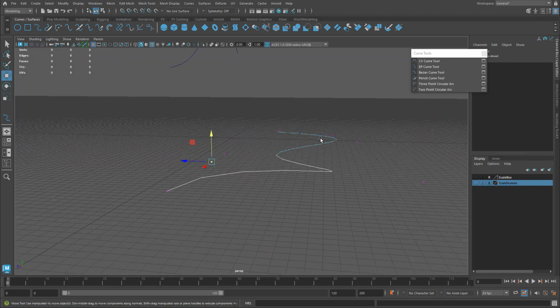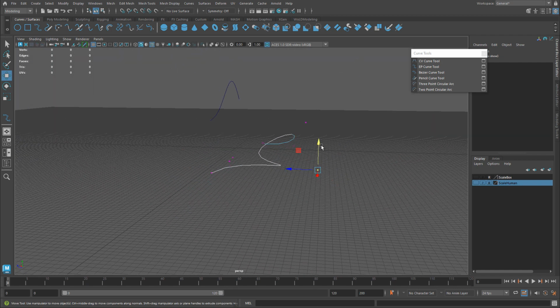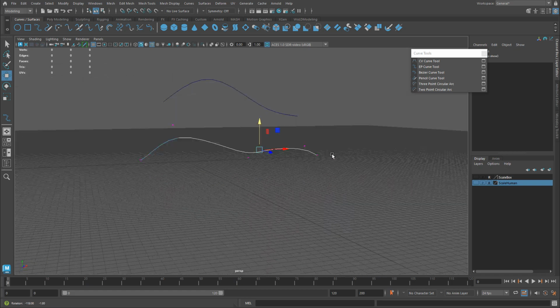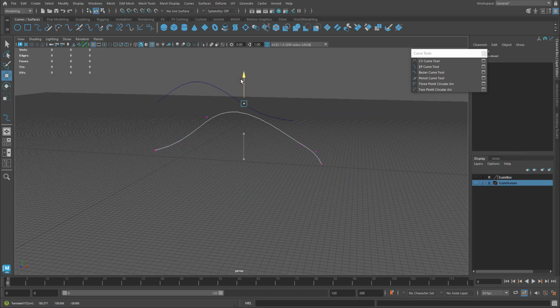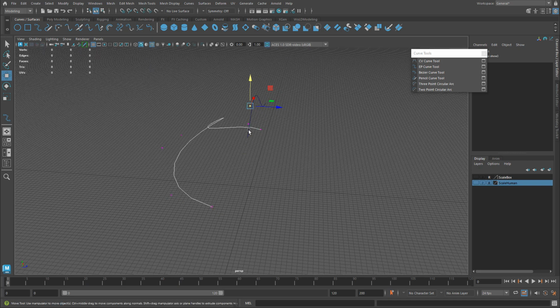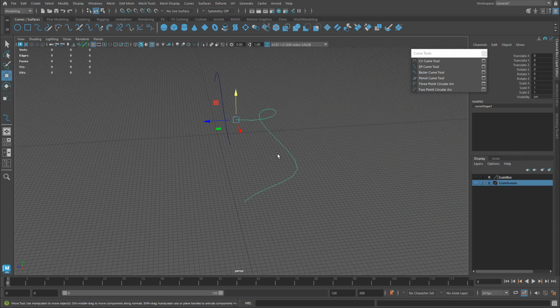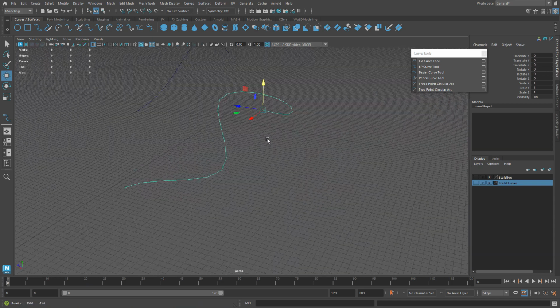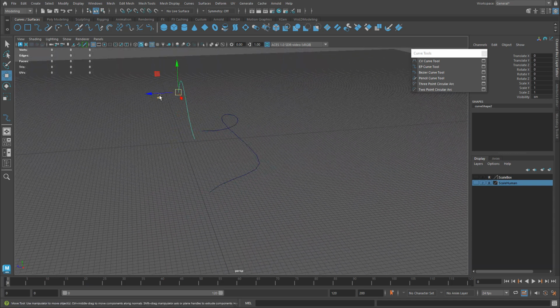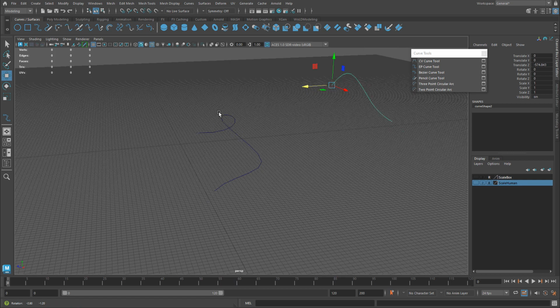And in this case, you can actually drag it and modify it so it's not flat on the grid. You can just drag it up and down and give it some 3D dimension, so it's not on top of the grid. And then once you're done modifying it, right-click hold, go back to object mode, reselect the curve, and now you've modified the curve and you can do something with it. Let me just drag this curve just a little further away.